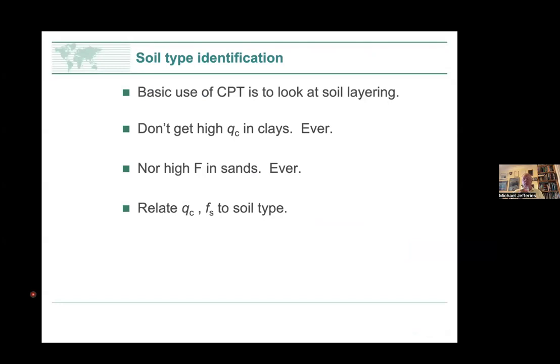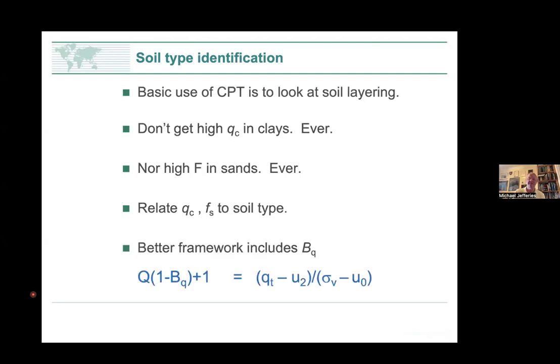Okay, next thing. Soil type identification. The basic use of the CPT, or was, to look at soil layering. You don't ever get high tip resistances in clays, ever, nor do we get high friction ratios in sands. So the idea was perhaps we can relate what we measure with the CPT to soil type. And various charts were developed doing this.